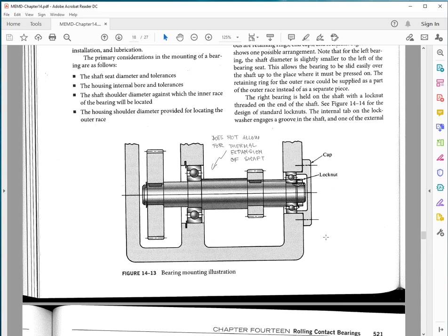When you design with bearings, you need to account for a number of things. Firstly, how you assemble everything together. If you look at this drawing here, which has some flaws, and I'll discuss them. So things like being able to reach where this retainer ring is, being able to have the full assembly placed together with the bearings and secure the bearings in place.